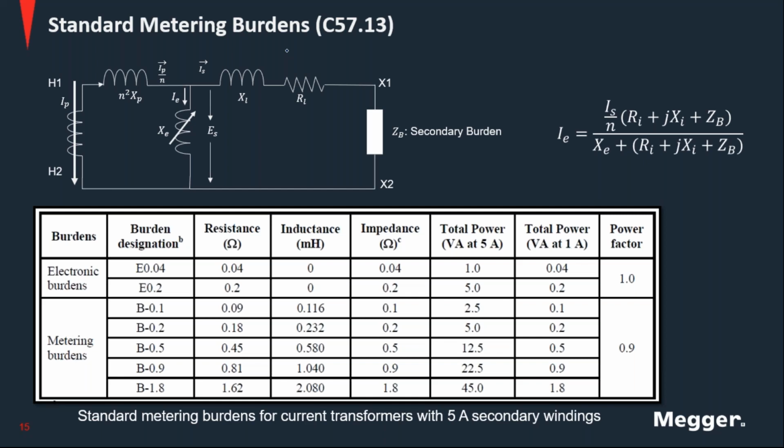Also, sometimes you have damaged windings. You have issues with shorts between windings, and sometimes those are only detected when you drive the secondary of the CT to a high enough voltage to cause those shorts to show up. That's one of the reasons why, even though it's often done, testing the CT with just a very low voltage to obtain the saturation curve is not really recommended.